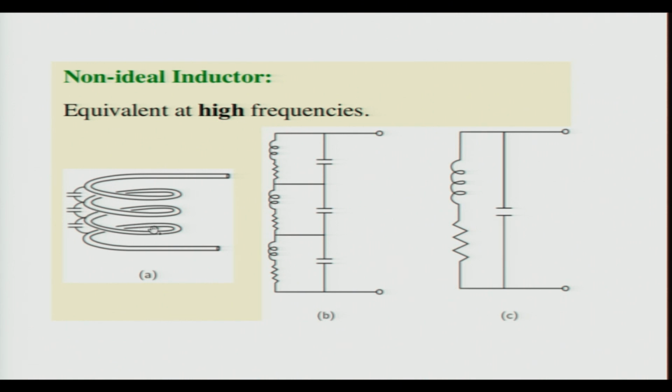So, it is important to know whether there has been any physical displacement due to faults, etc. And one of the ways to do it is to test the transformer without opening it up, because the transformer is usually in oil for cooling as well as insulation. So, this whole setup is in oil, and you do not want to take it out and analyze it that way. You can actually do these same frequency response tests on the transformer and find out whether there has been a change in the characteristic frequency at which, for example, the transformer turns from inductive to capacitive.